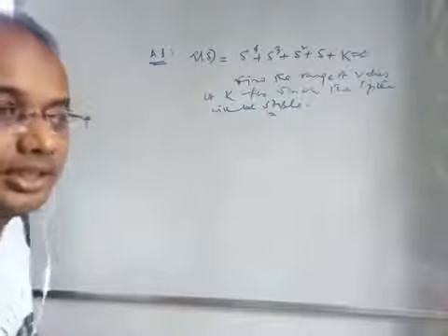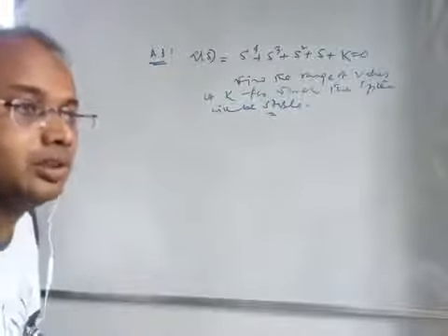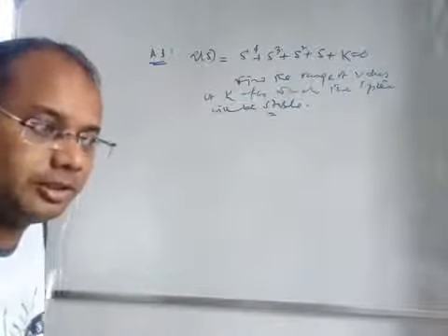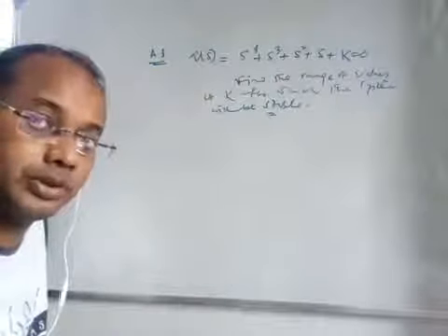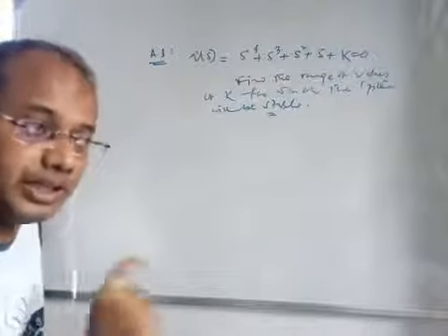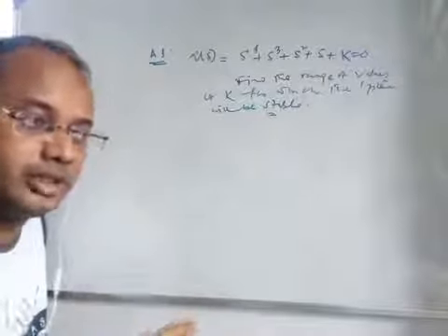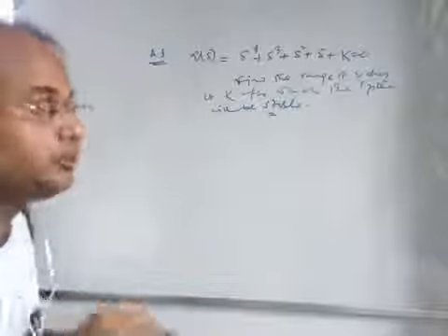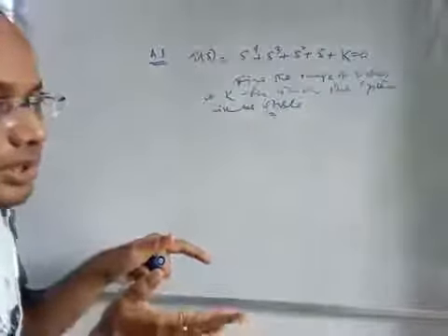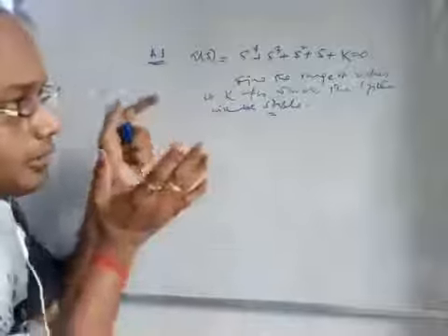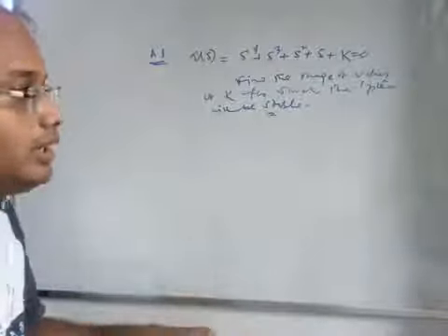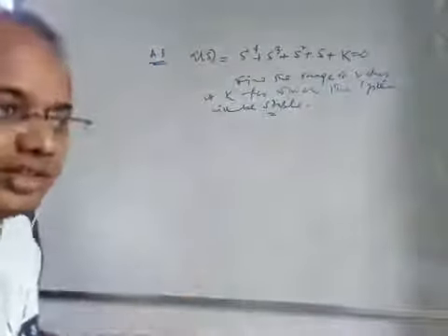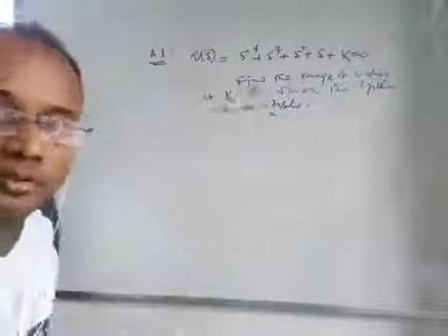So while getting the solution, you may have to overcome the issues of special cases. There may be situations where in any row all the elements are 0, so you have to consider the auxiliary equation. It may be possible that a row contains only the first element 0 but the rest of the elements are present. In that case, you have to consider epsilon and so on. By considering all these special cases and rules already discussed, you complete the Routh array. From the completed Routh array, taking all the elements positive to make the system stable, you can get the value of k.